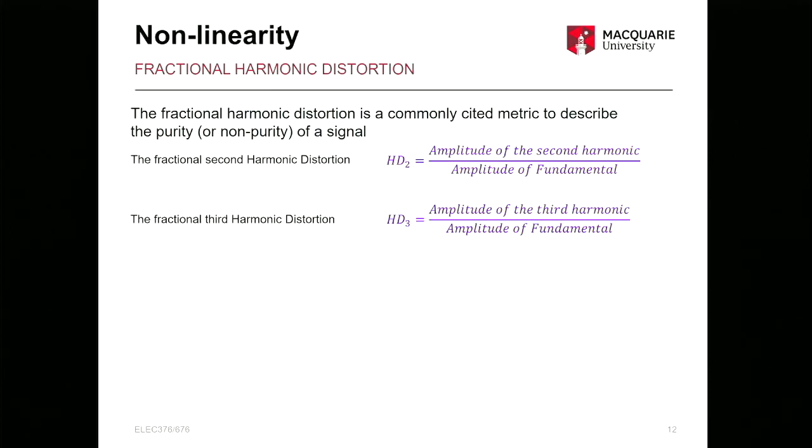Any questions? These harmonics, as we are calculating, these are in the time domain, right? We are looking at harmonic distortion. These are in the time domain, but we can't really see that distortion in a time domain signal. So usually you go to the FFT or the Fourier transform, and then find out the amplitude for each component, each sine component, right?